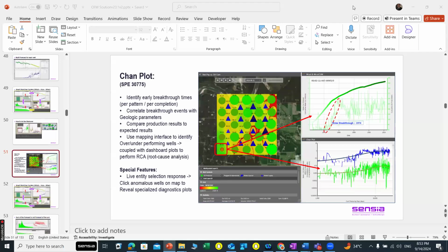When you do water flooding, you have to look for injectors. This is also when you do workover, because you need to understand the time to breakthrough. So you divide your field into different patterns or segments, and you relate your wells by streamlines. This is another topic we can talk about later. And then you have to do balancing. You have to see how much you inject versus how much you produce. We call it VRR.